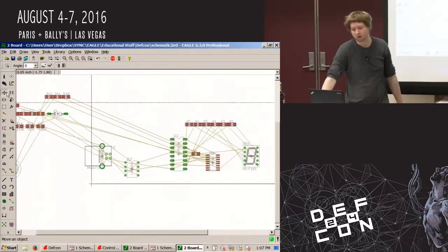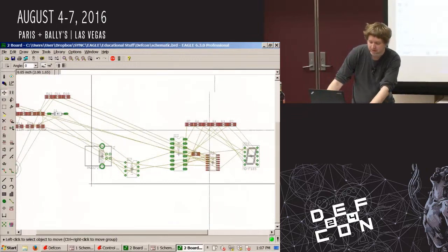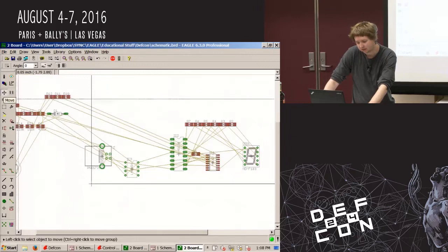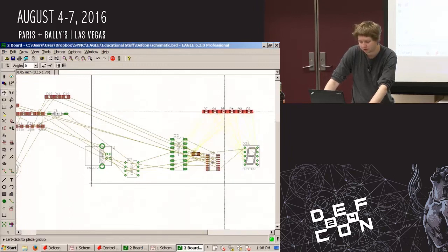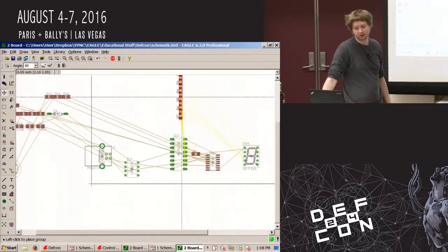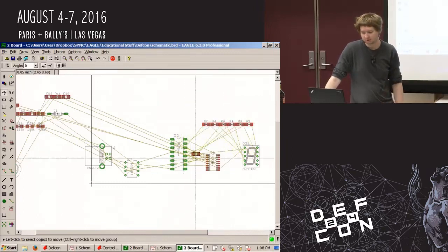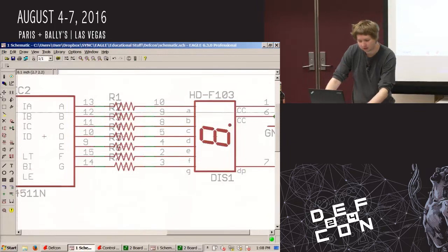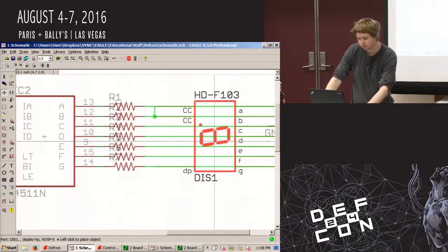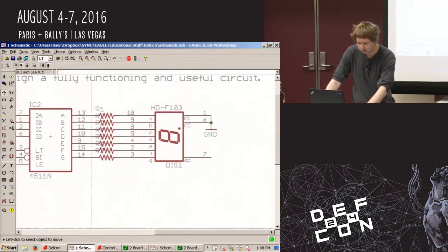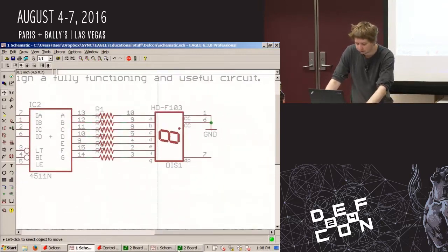Yes, you can rotate. I'll do it with this bunch here, but it works exactly the same as with only one. With the move thing selected, you can hold down Control to select everything, and then you can right click, and that rotates it by 90 degrees. If you middle click, it'll put the component on the other side of the board. In the schematic, if you middle click, it'll just flip the component. So it can be useful if a component isn't quite oriented correctly.